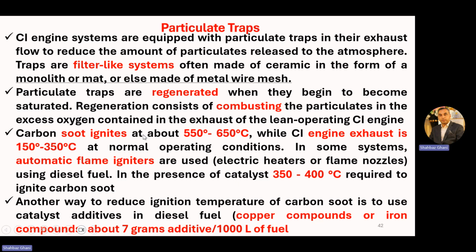Carbon soot ignites at about 550 to 650 degrees Celsius. These solid particulates trapped there ignite at 550 to 650 degrees Celsius, while CI engine exhaust is 150 to 350 degrees Celsius at normal operating conditions. So the exhaust temperature is quite low.